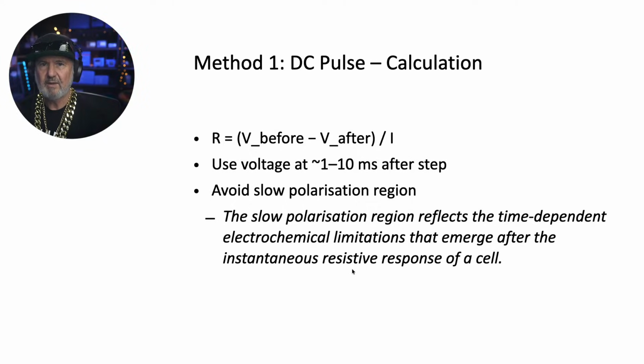And use the voltage at around about the 1 to 10 millisecond step. So that's why an oscilloscope is pretty handy, because you can actually see the time base. And at that sort of 1 to 10 millisecond step change, see what the voltage is.